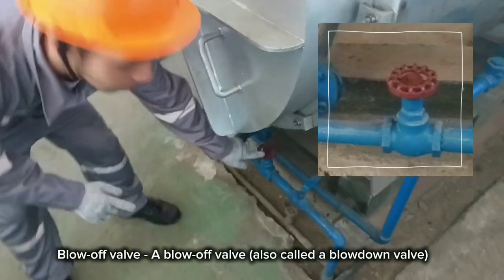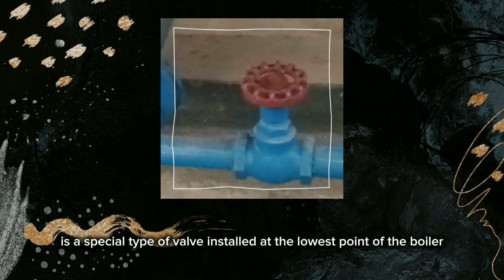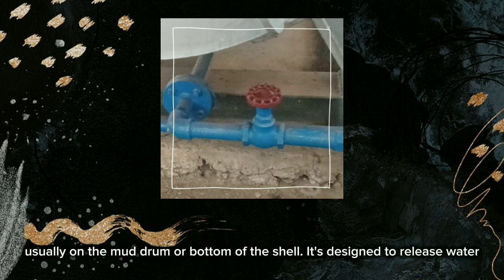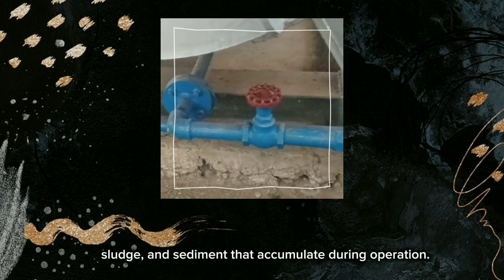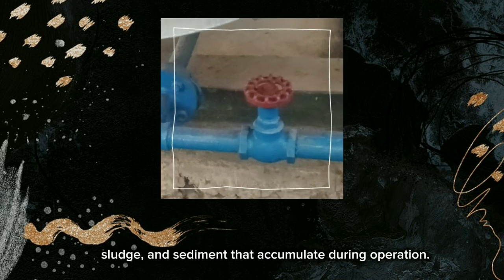Blow-off valve. A blow-off valve, also called a blow-down valve, is a special type of valve installed at the lowest point of the boiler, usually on the mud drum or bottom of the shell. It's designed to release water, sludge, and sediment that accumulate during operation.